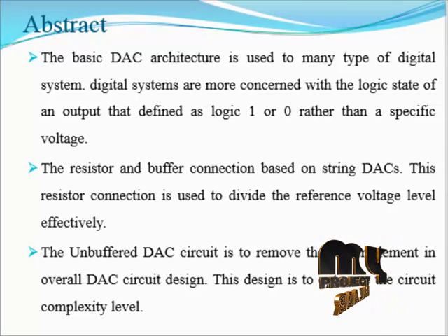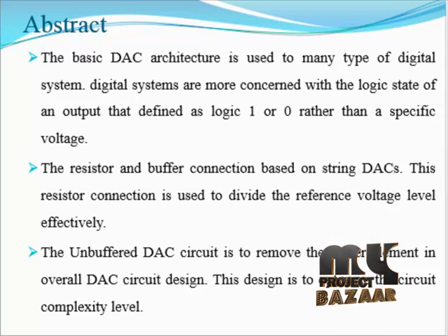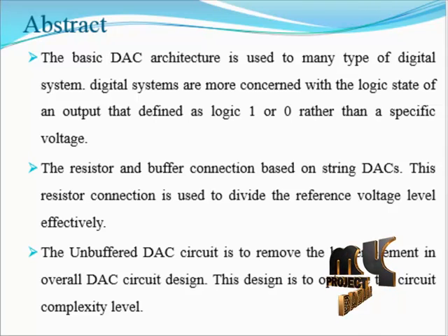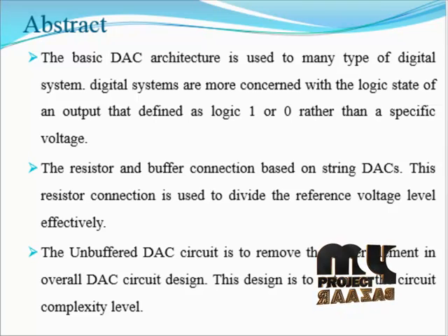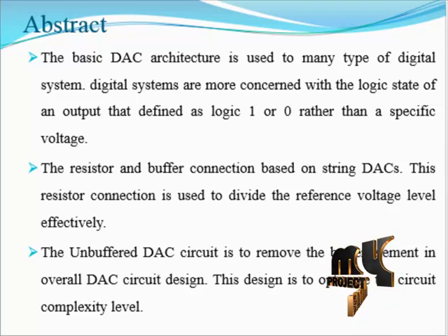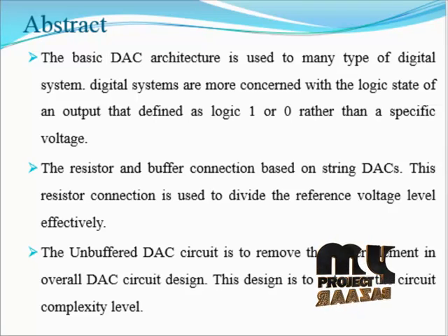areas. In our process, an n-bit two-stage DAC includes an m-bit resistor string DAC. The resistor DAC and the n-bit DAC with embedded resistor amplifier are connected in series, where m is an integer and n is greater than m. Both processes are string processes, giving high resolution digital to analog converters to realize accurate external compensation of the scheme and the sense of the various electrical characteristics.